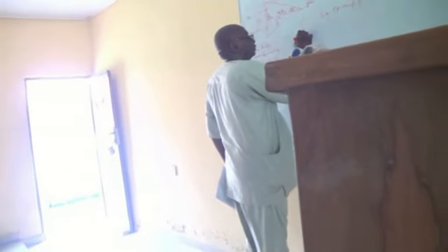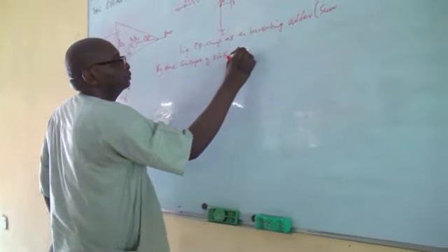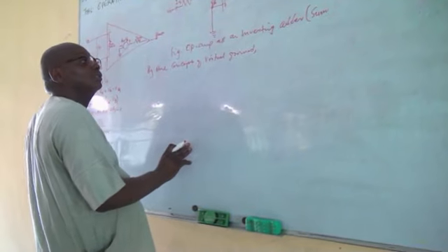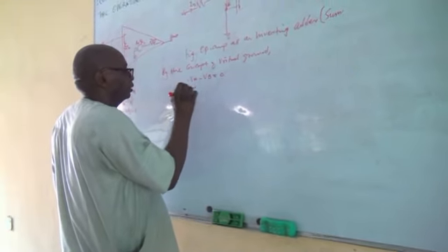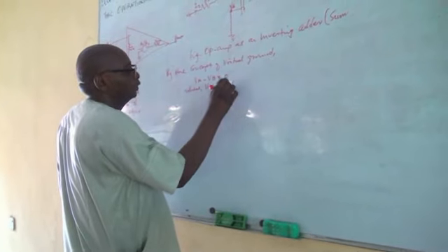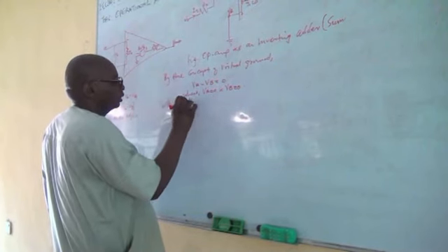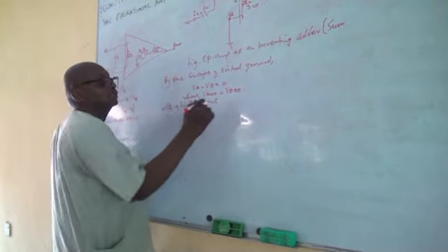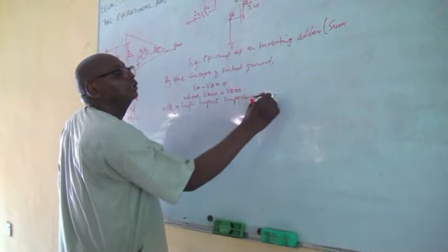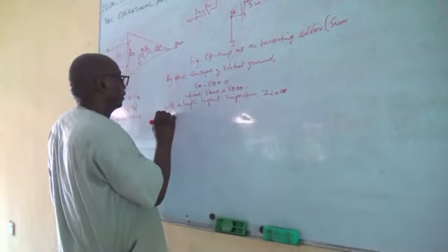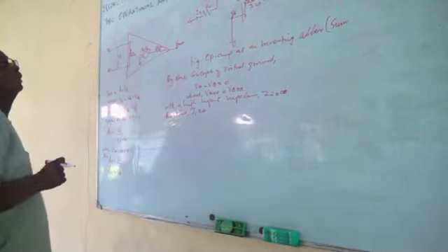So by the concept of virtual ground, what we're going to have is VA minus VB equals 0, where VA equals 0 and VB equals 0, with a high input impedance, Z in tends to infinity. Therefore, I1 equals 0.